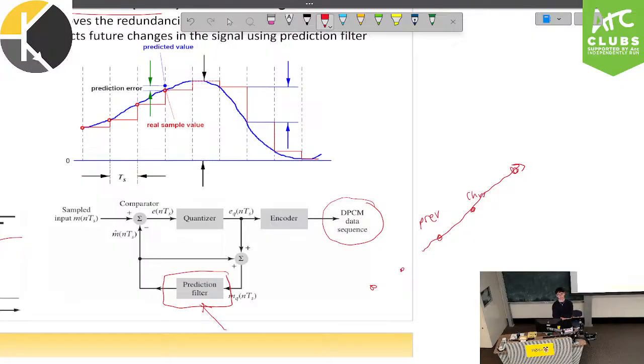It predicts the next value, and then it has the quantized value which it gets from the PAM. And then it compares the two, and based on that, it sets the value. It doesn't ever look at the value that it transmitted itself, because then that would kind of throw it off. It would only look at the samples that it's received so far, right? And then the sample it receives, it changes that to the predicted value? Yeah. Cool.